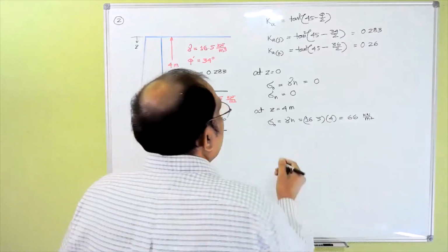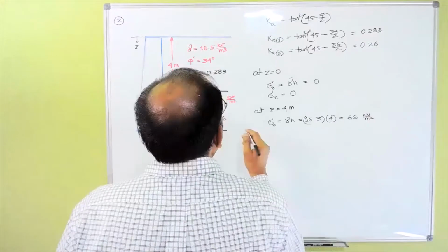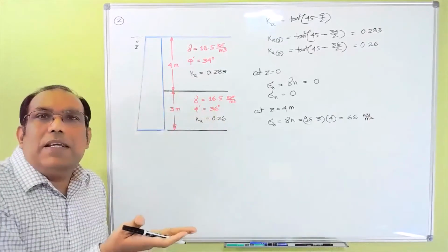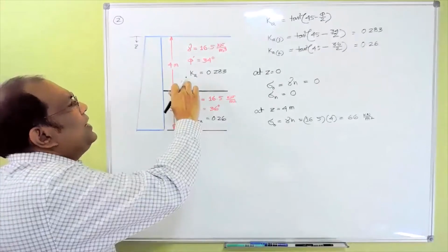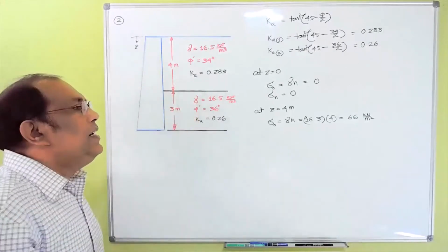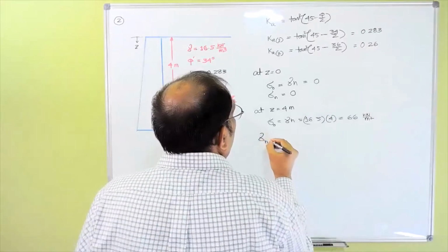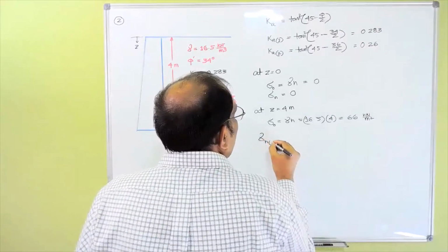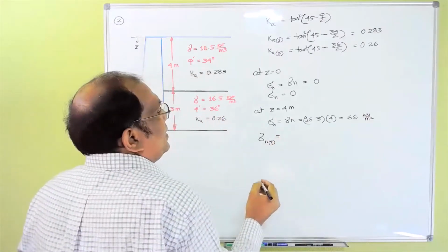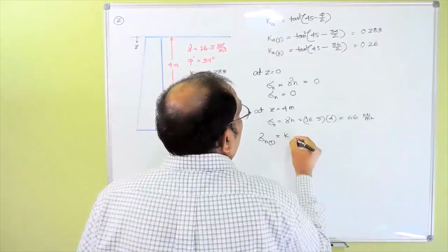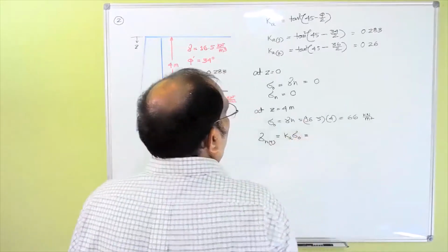So your effective stress for the top layer, just a little bit above this interface here. So this one is like this layer here, right? So your sigma H for the upper layer, let's say our top layer, is actually your Ka into overburden stress.